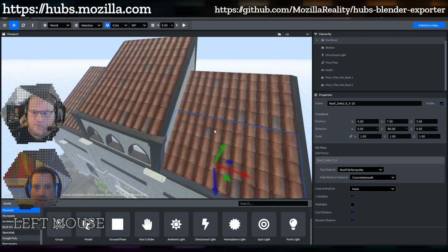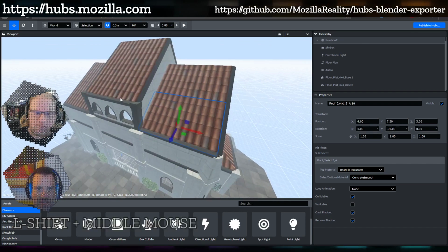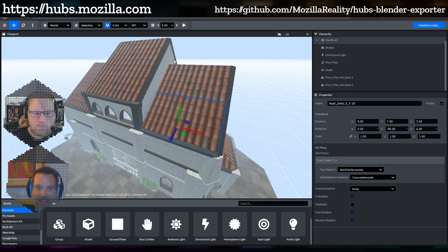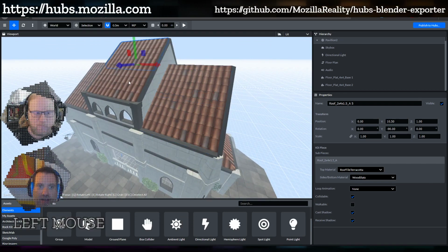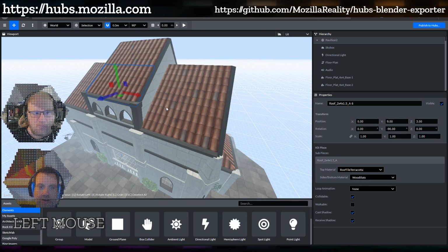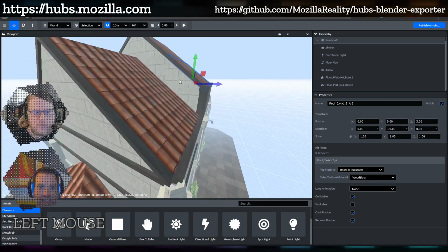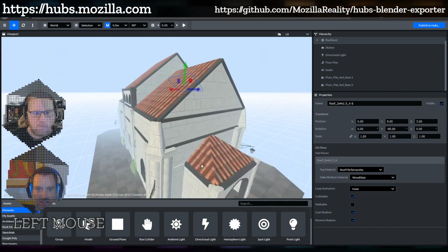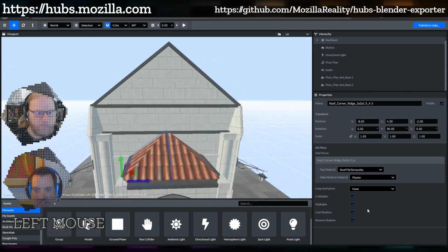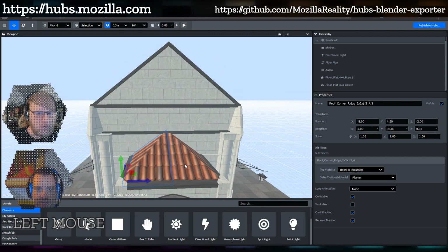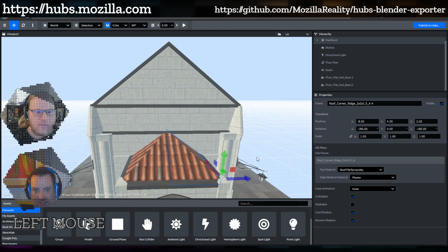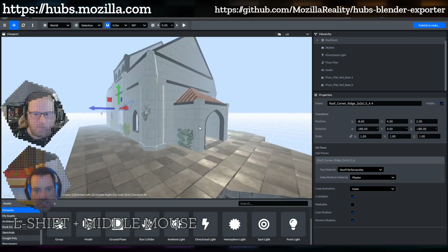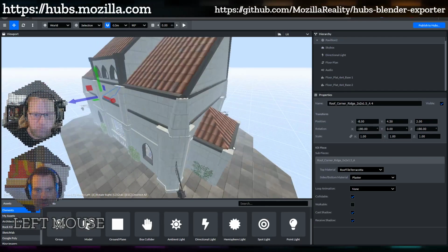And bear in mind, you might be asking, what about all these little beams? Should I turn it off? Probably. But at the same time, the settings of the floor plan are going to dictate how big an object has to be before it'll even consider generating on it. So if it's not an issue, if you don't see floor plan being created somewhere you don't want, then you can leave it alone. It's not a huge deal, unless, like Dom said, you start running into memory problems and stuff.